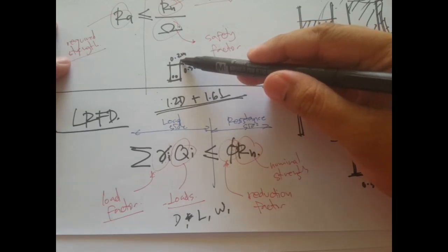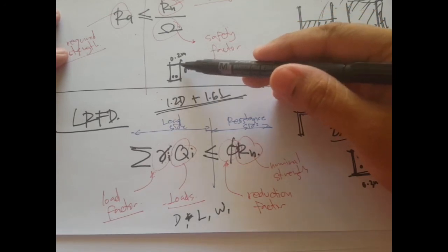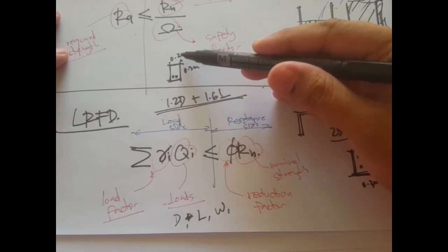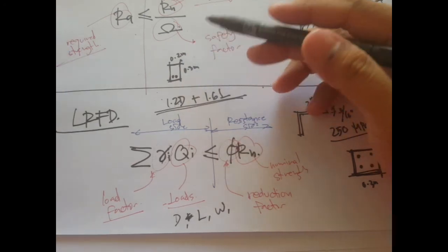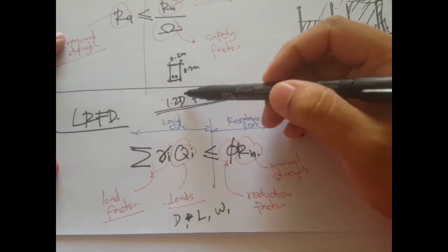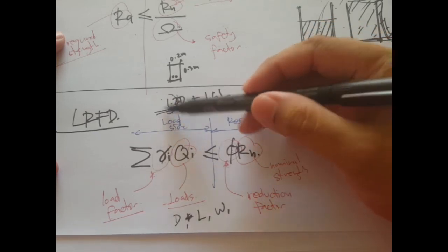Of course in the drawing it's going to be 0.2, but in actual construction it might not be that accurate. So that could be, let's say, 0.19 or something. That's why you have these factors on the dead loads.